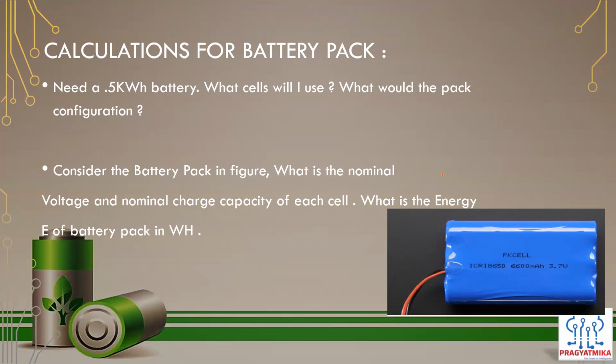So it is the voltage that is necessary once we are talking about the battery pack. The voltage is the necessary factor, and then the capacity or the energy. Current is not required; the current could be varying depending on your C rate. Current depends on the application, but for the battery pack, it would be the capacity or the energy. That's what I should always say. So this is not the right question actually.